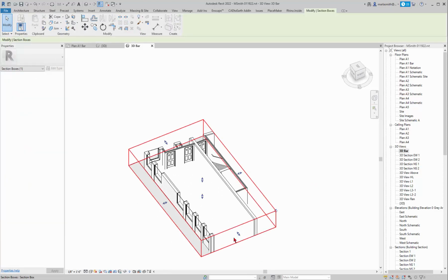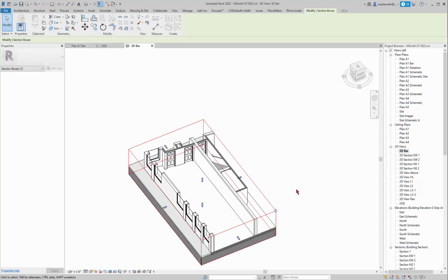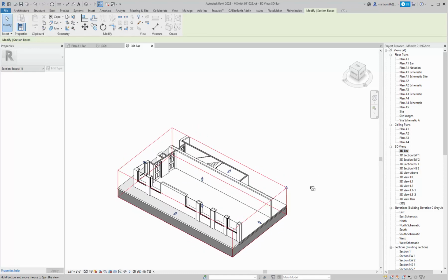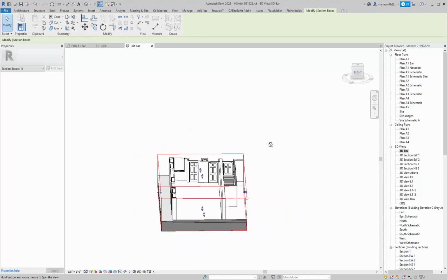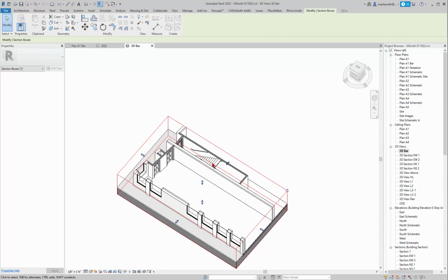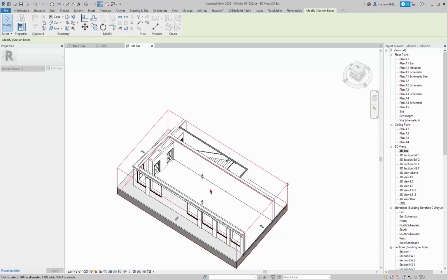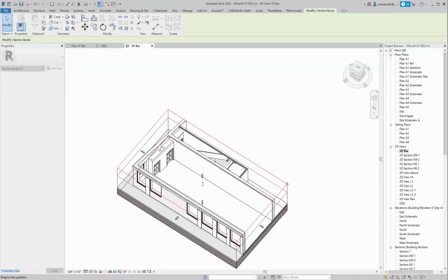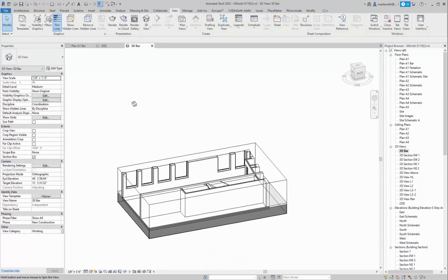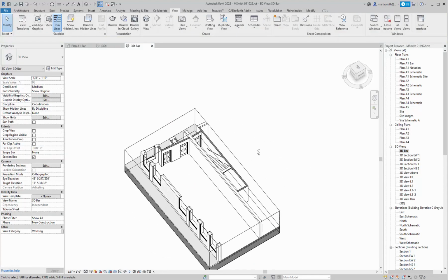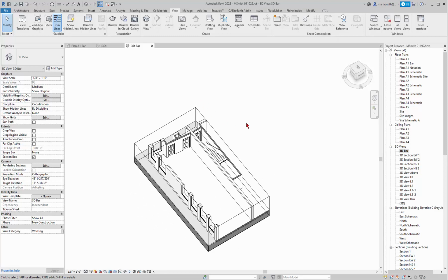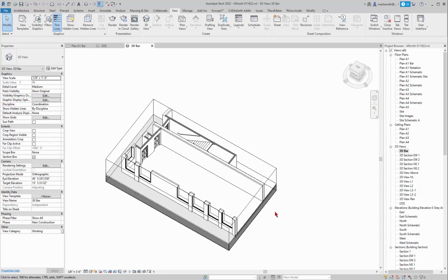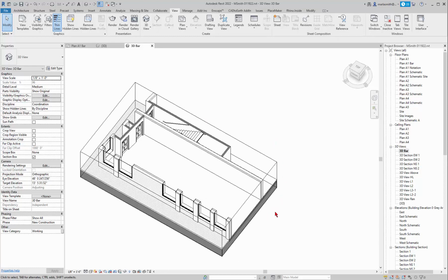Now I can go and pick this box and kind of pull it down a little further, and you can see it pull down so you can see where it's hitting the floor and all that kind of stuff, and adjust it a little bit, and either vertically, so I could go up higher because that is a 15-foot floor plate at this point. So you can see now I've gotten to the second floor, but I can pull it down a little further, or even a little further where I'm kind of halfway through the windows. And it's kind of up to you. This is a working view for right now. We might use it to print, but right now it's a working view. So once we get all this stuff set up, you can start to manipulate these and use them to model the bar. So we'll do that next.